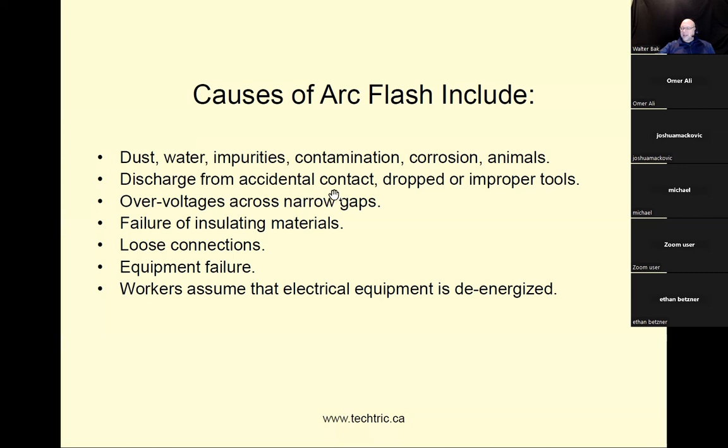Discharge from accidental contact, dropped or improper tools. Whenever there are some works being done on high voltage or high energy equipment, there are specific procedures, and that varies from one company to another, to make sure that the risk of a tool falling out of your hand or making contact with the electrical equipment otherwise is minimized or eliminated, because tools can be conductive, and if they fall onto the electrical equipment, they can cause an arc flash, right?